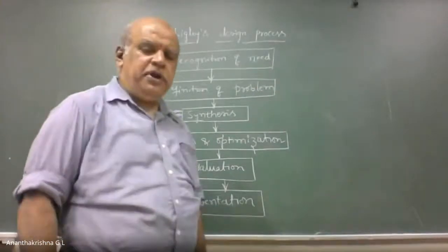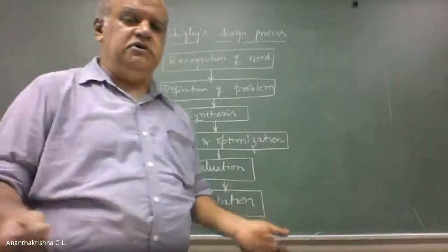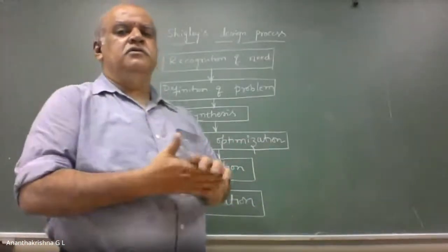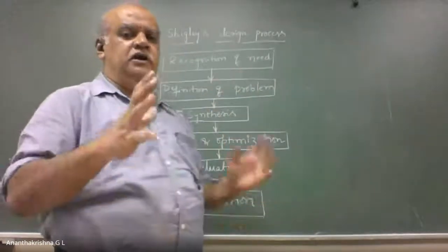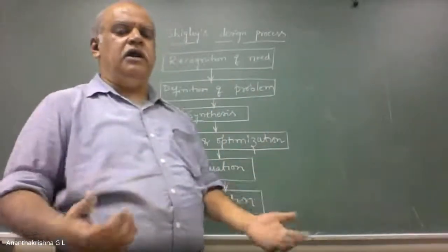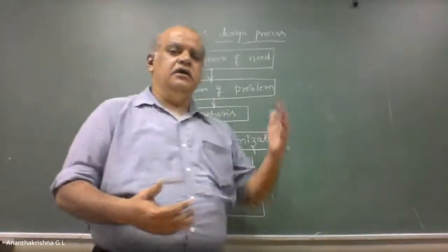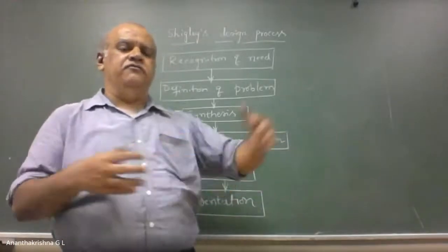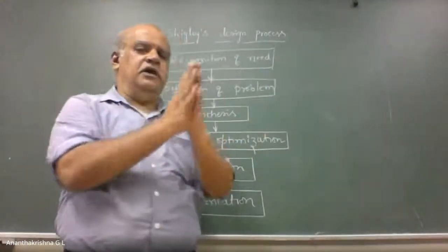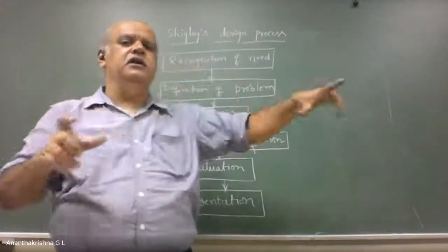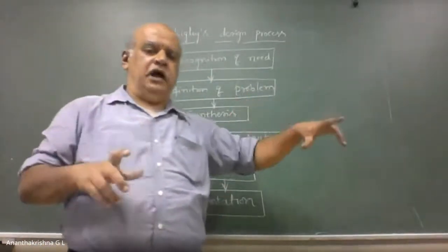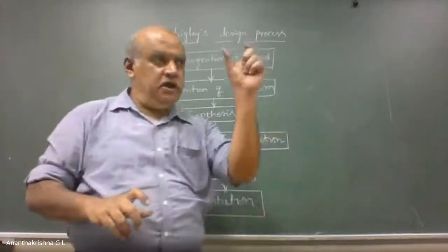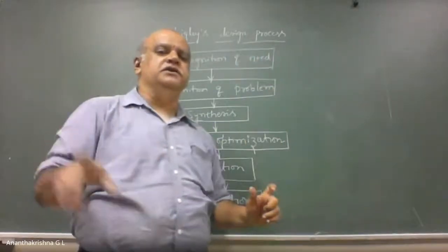No. See, you have various data handbooks, like the gear data handbook and the machine design data handbook. The formulae are given in the data handbook to calculate. How they have arrived at them is essentially by continuous evaluation, experimentation and past experience. They would have done lakhs of components and arrived at how a component will behave if I take this much. So they have an empirical relation developed over a period of time. If the design is based on the equations that we take from data handbooks, such design is the empirical design.